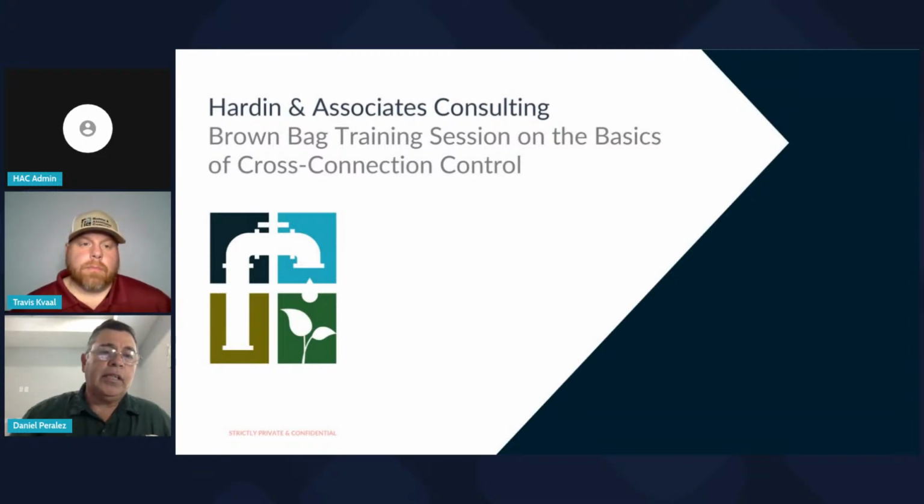We need to understand what a customer service inspection is. It's an inspection of the private distribution system. When we say private, that's inside the property. What ultimately a CSI inspection is doing is identifying potential or actual cross connections inside the private distribution system to protect the public drinking water and the customers from any contaminants or pollutions getting into the drinking water supply. That's basically what a customer service inspection is, and it is mandatory.